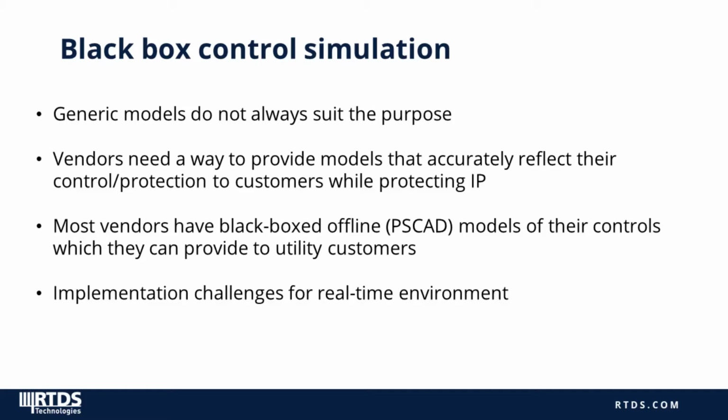This concept is very established in offline EMT simulation. So most vendors have a black boxed PSCAD model of their controls, which they can provide to utility customers. So in the case of a new DER project or a power plant controller installation, the utility requests that model from the manufacturer, and they can then integrate that model into their PSCAD grid model for testing.